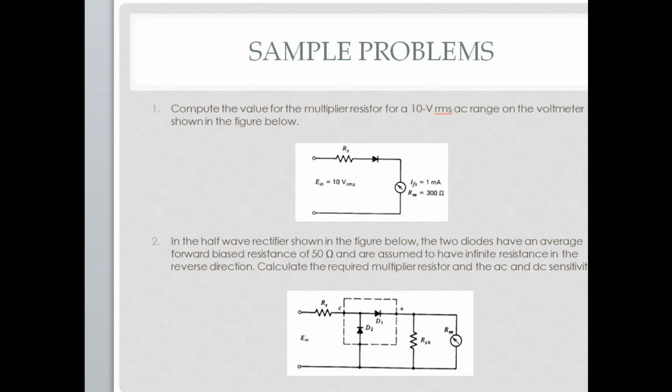So just to give a brief background on why there needs to be rectification when you are to implement your AC meter. I hope you've read your module already, but cut the story short, if you're going to implement the measurement of AC voltage or current, you cannot basically just make use of the D'Arsonval meter movement directly without any form of rectification in it.